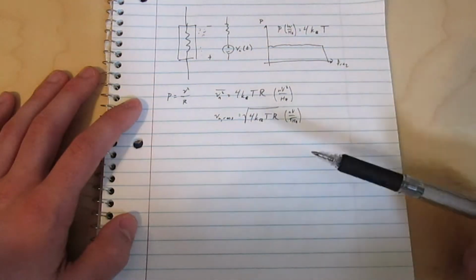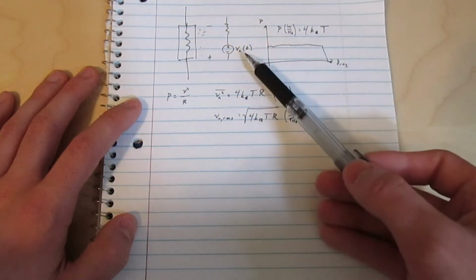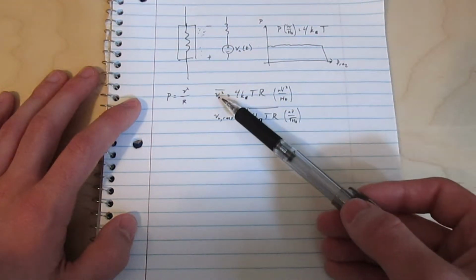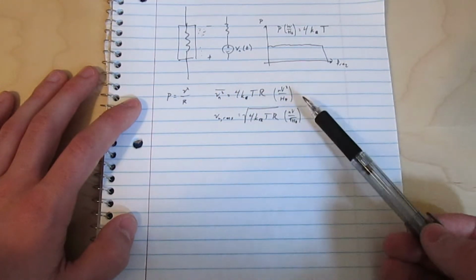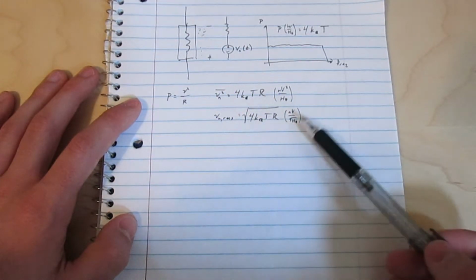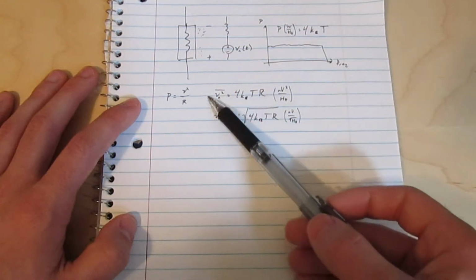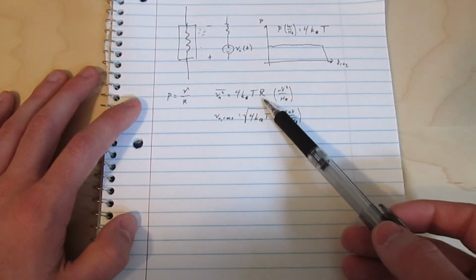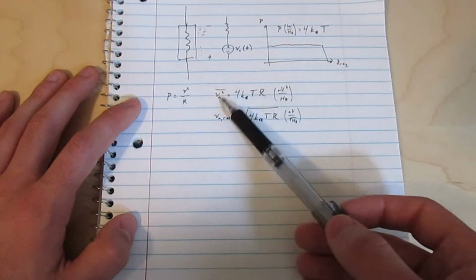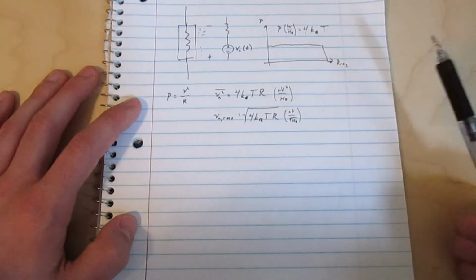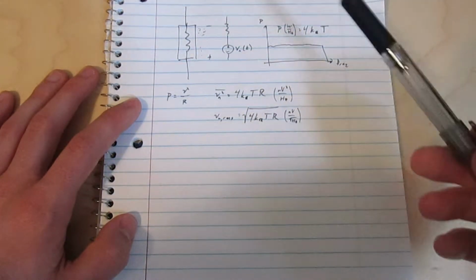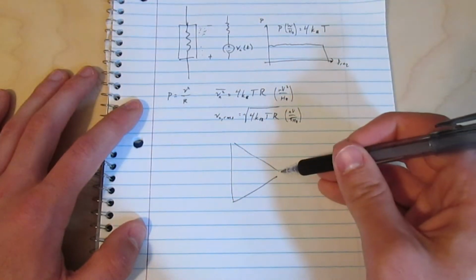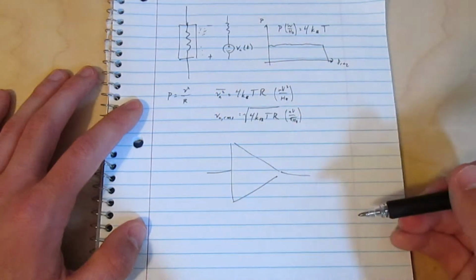So here we have a few different ways of representing this noise voltage. We could talk about it as an actual voltage that changes over time. Or we could talk about the mean square voltage per hertz, or we could talk about the RMS voltage per square root hertz. Or I could start with, say, the mean square voltage and come up with an equivalent resistance, which is basically how large would a resistor have to be to cause that much noise. And in this video I'm going to sort of be going back and forth between all of those, based on whatever's more useful to me at the time. Alright, almost there. One more thing I need to talk about is the concept of input referred noise.